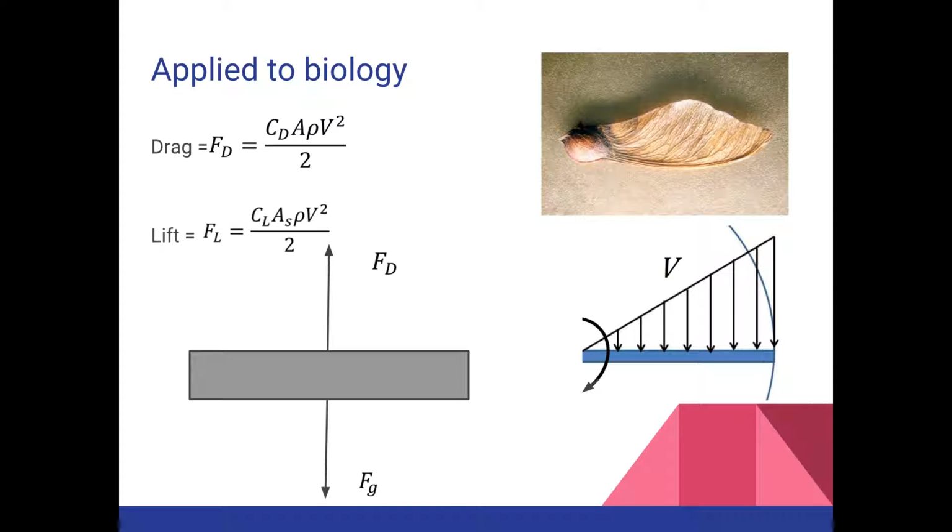As we looked into this comparison, we drew parallels to helicopter blades, and we were actually able to find some technical sources on helicopter blades and the principles there. We found that the main two principles in play were drag and lift. Obviously, both of those counteract gravity. In both cases, for the seedling and for the helicopter, gravity acts in the downward direction. Drag acts on the body upward, but because you have this rotating fin or airfoil type shape, you also get lift that is counteracting gravity.